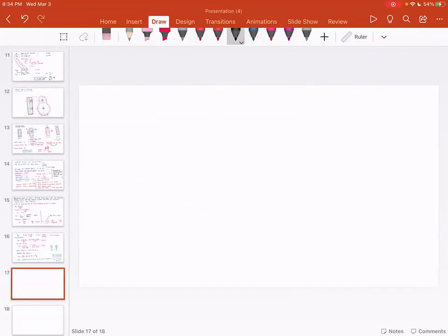So next step is checking gear for wear. Let's find out the reduction ratio or velocity ratio. It is also called the reduction ratio, which is the diameter of the gear divided by the diameter of the pinion. Diameter of the gear is 320, diameter of the pinion is 80. So the reduction ratio is 4.